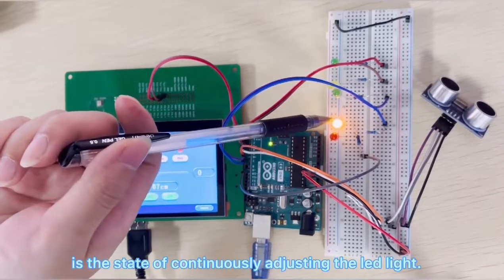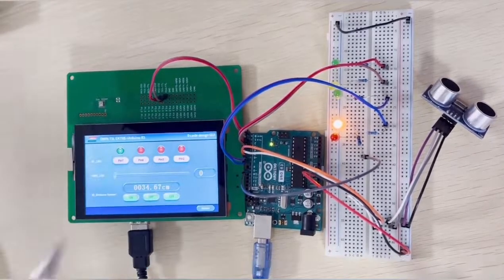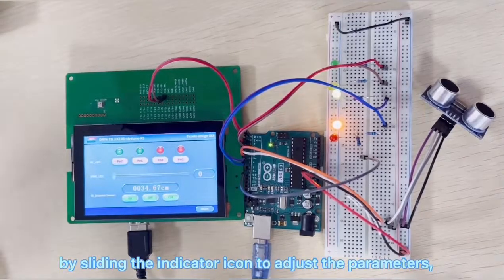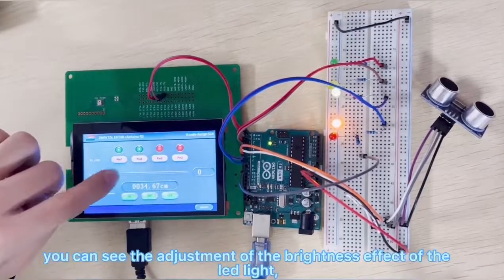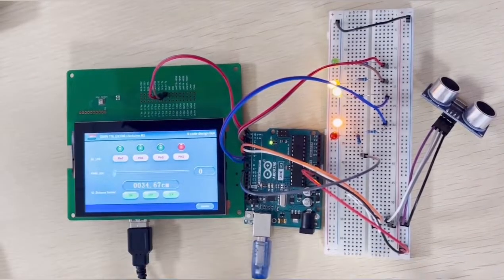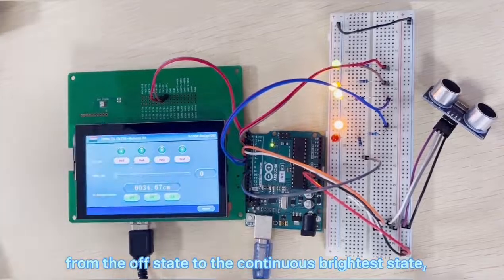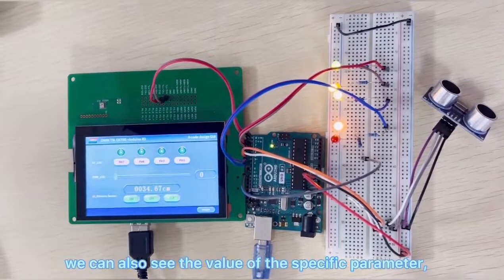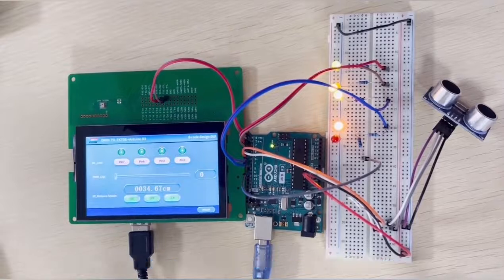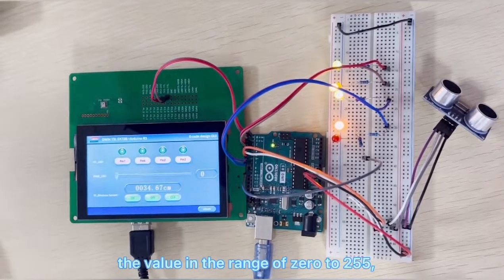In the middle is the state of continuously adjusting the LED light. By sliding the indicator icon to adjust the parameters, you can see the adjustment of the brightness effect of the LED light, from the off state to the continuous brightest state. From here we can also see the value of the specific parameter, in the range of 0 to 255.